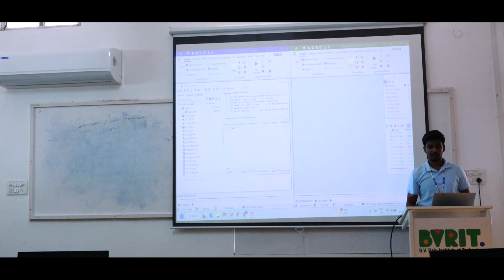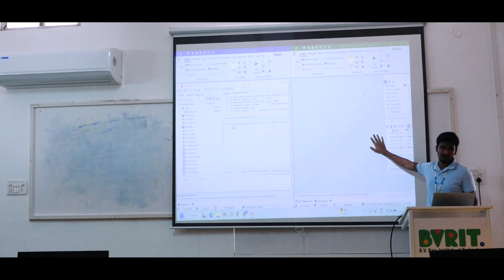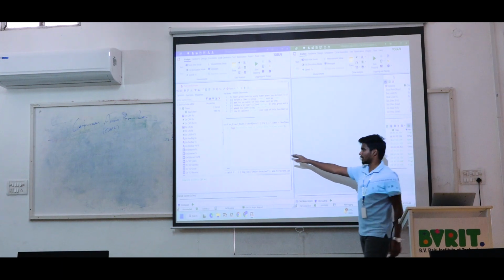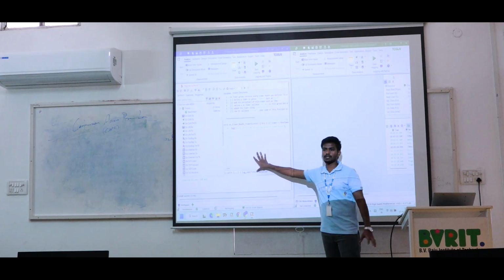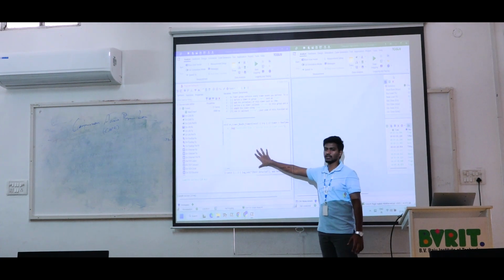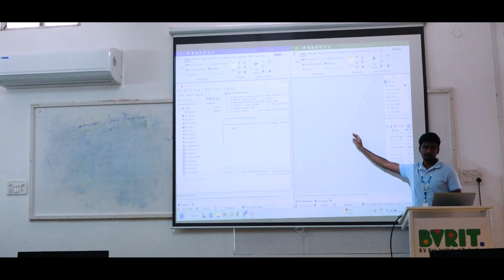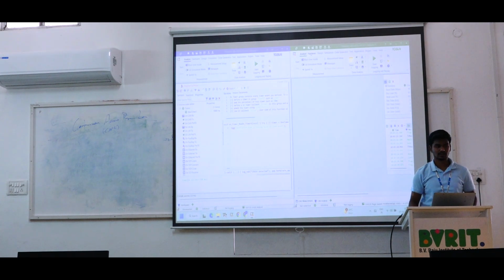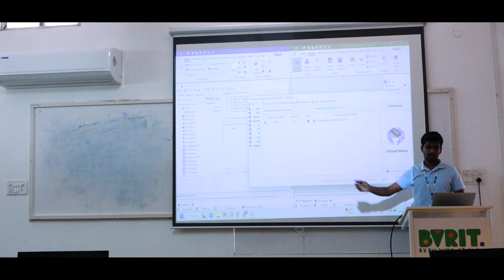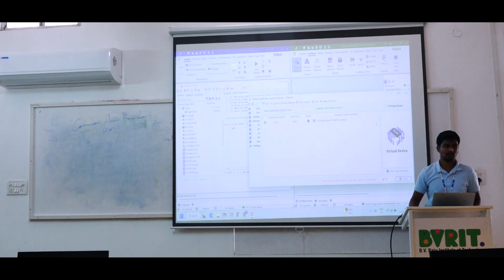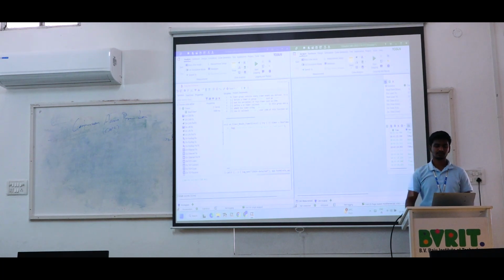Go to the new tab. This is our newly opened tab. It is our already existing tab we created. In this tab we already mapped some hardware configurations and channel one of the virtual device, so don't check with this one. Go to the new tab. In this tab we open the hardware configuration. In this folder, please select the channel selection of what we previously selected in our existing tab. We previously selected the virtual device of 1 CAN channel 1. Okay, so next we go to analysis. Please upload your database in the second tab.